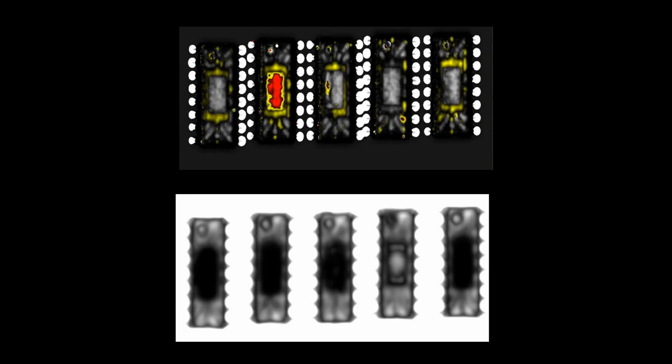Scanning acoustic microscopy is useful in counterfeit detection. These 5 parts were selected from a reel at random. We were looking for evidence of counterfeiting. The top image is reflective mode. This image shows delaminations and cracked ice. The bottom image is transmission mode, which shows that 4 of the parts are fully delaminated. When this many parts are bad, they are counterfeit.